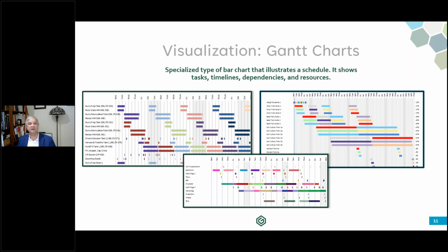If you receive a Gantt chart output from your modeler, and every batch looks identical, and they're marching with precise start times, 8:30 every morning the batch starts, that kind of thing, I would question that and start drilling in to find out why aren't we seeing some variation here.